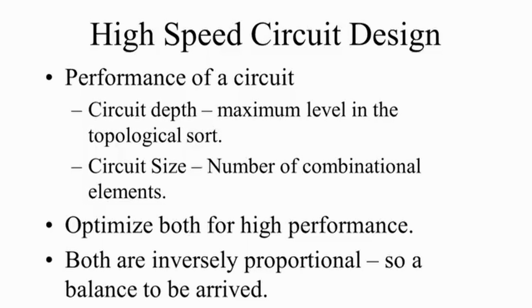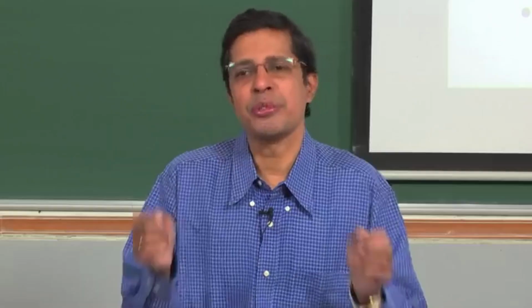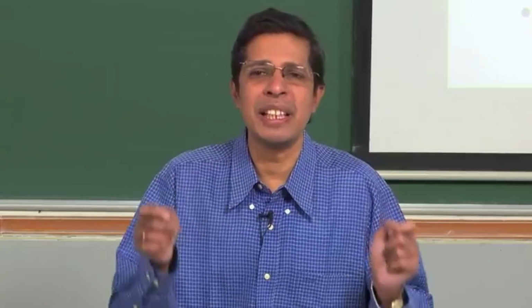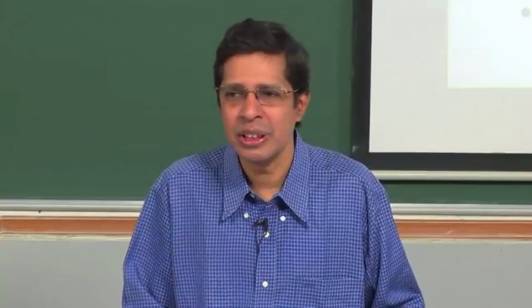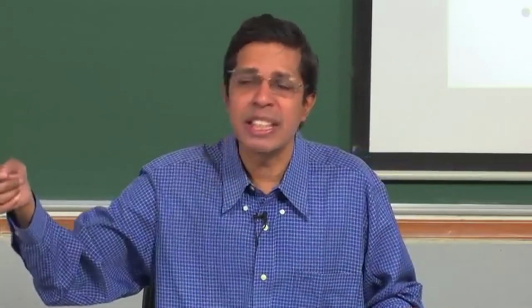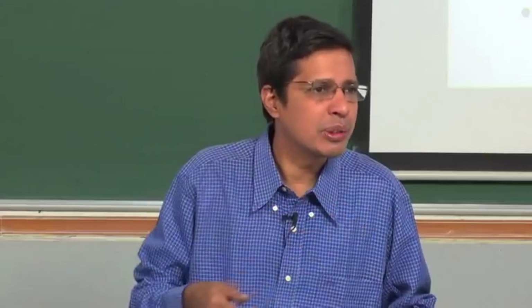Now, when we want speed, if I take a circuit, how will you define the speed of the circuit? The speed is determined by the delay incurred in the circuit. So how do you measure the delay in the circuit? When I change an input, any arbitrary input, what is the time required for the output to change for the corresponding change in the input? The maximum delay is what we call the delay incurred by the circuit.